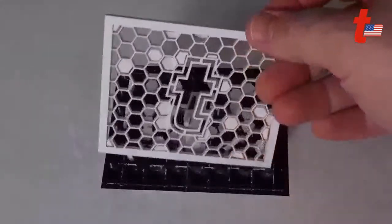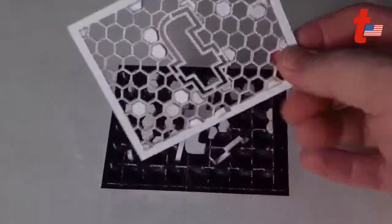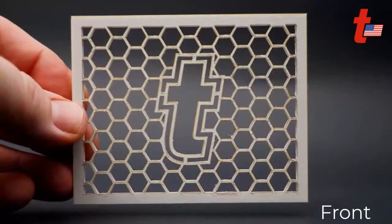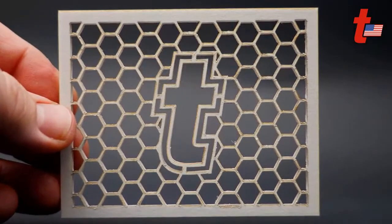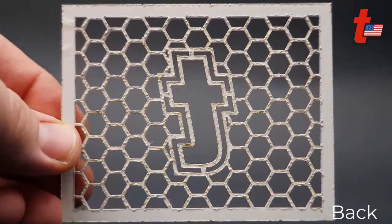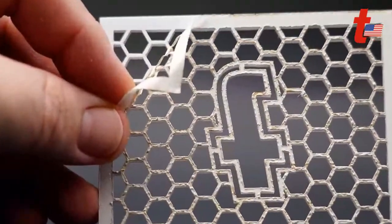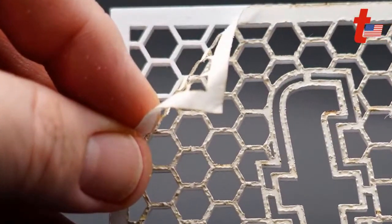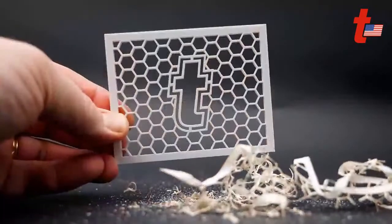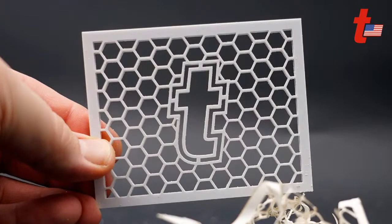Now, the back side of this is going to be rough. This is why the mask is needed, you can see almost a slag type plasticky residue. So there's the front, a good photo of it, and then I'll show you the back as well, right out of the laser machine. This is why the mask is needed, because all those little plasticky slags, if you don't mask it, will stick to it. If we go ahead and peel the mask off now, we're able to take out all that extra residue, and it literally just breaks away.